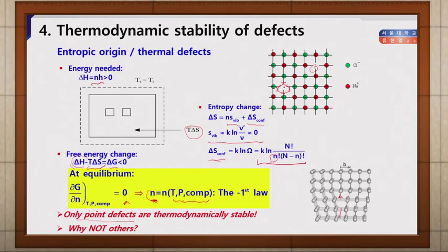So in this sense, by controlling thermodynamic variables, you can control the defect structure of your system. And then consequently, all the defect structure sensitive properties can be controlled by these defect concentrations, which are in turn controlled by thermodynamic variables. So this is how defect structure sensitive properties can be controlled by adjusting defect structure via thermodynamic variables.